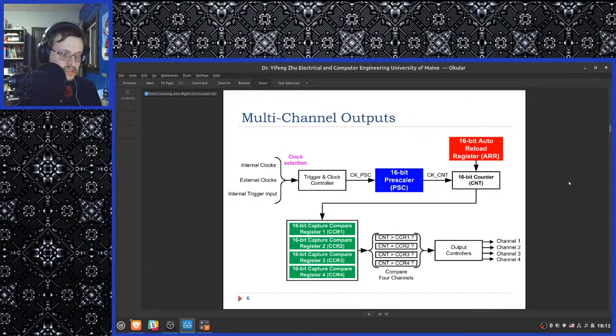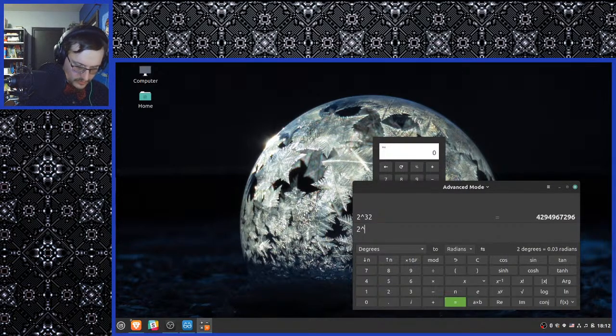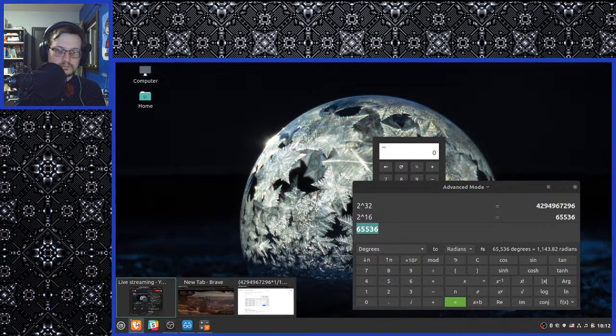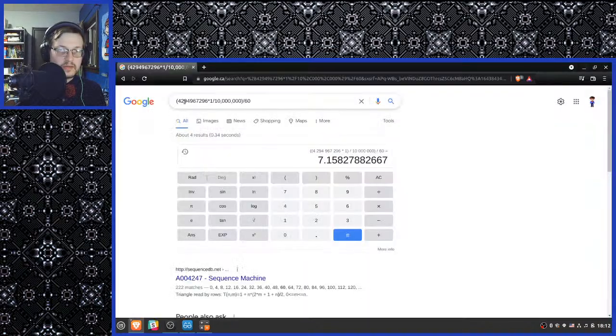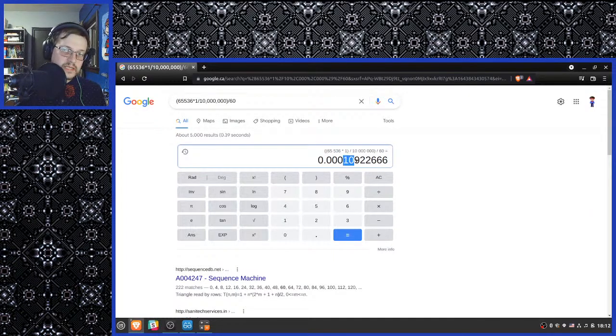Usually there are 16 bits in the timer register. Under 16 bits it's even more problematic. That would be 2 to the power of 16, which, if you didn't prescale that one, means basically your timer would reset once every 109 microseconds.